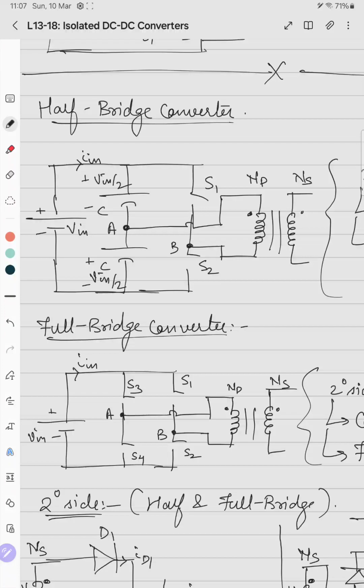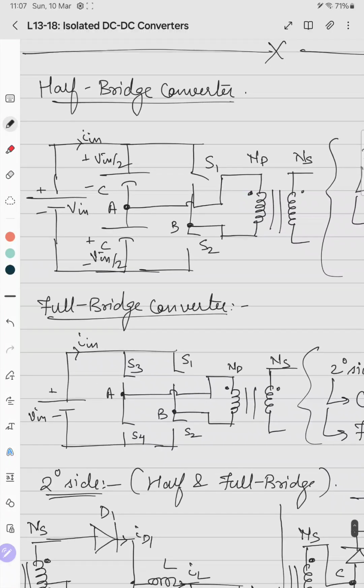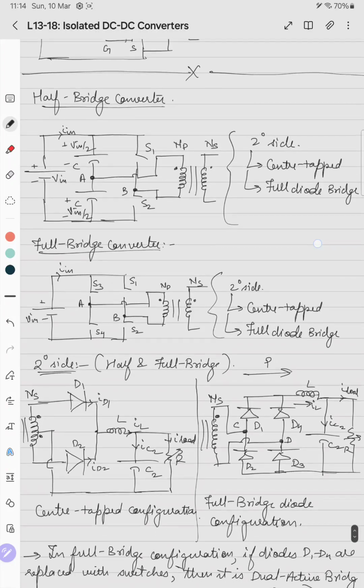That is, at the end of each switching cycle, the voltage rises and falls. There is an imbalance in the positive switching and thus in the negative switching. That is when the switch is off, it takes care of the overall compensation. That is, at the end of the cycle, the average value of the voltage drop across each of the capacitors is balanced, and it is maintained at V in by 2. So what happens here is that